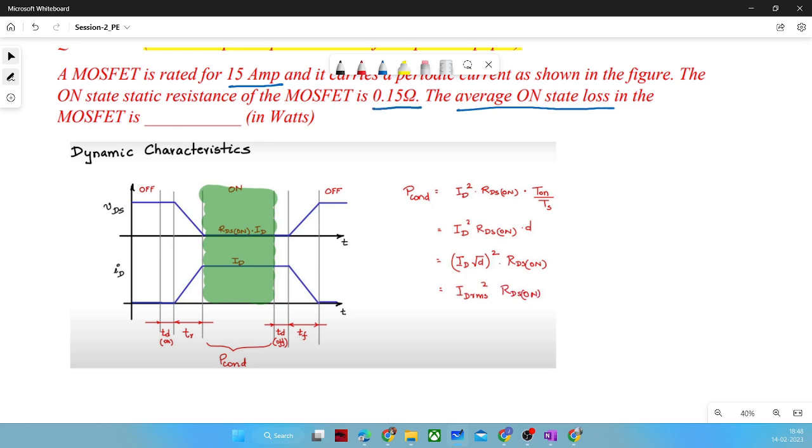And MOSFET is generally modeled as a resistor because VDS is ID into RDS(on), and this parameter you will easily find in the data sheet. It is a majority carrier device, for your information, and it can be modeled with RDS. So why is it modeled as RDS, and why are other switches not modeled as a resistance? Do you have any idea about that? Anyone?